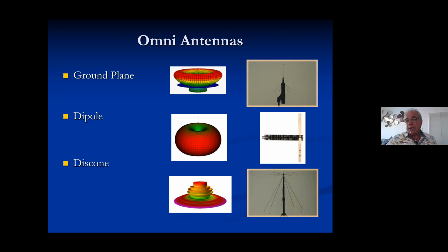By the way, I almost never use Omni antennas. These are very basic antennas. I use them when I do an RF sweep because I want to find out what's coming in from anywhere. Once I get into a show or rehearsal mode, it's all directional antennas.